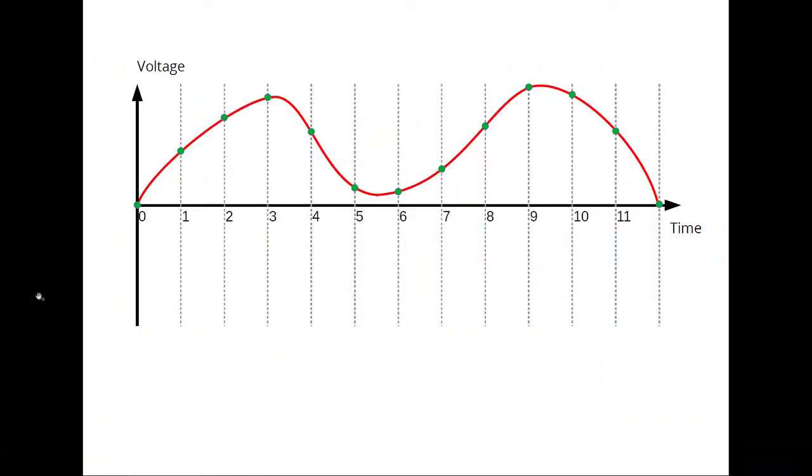So here we have a section of waveform which we've sampled, the samples being represented by the green dots, and we've numbered them for convenience. Let's say we want to play this sample back at 1.3 times the original frequency. Our output samples would now be the blue dots, which represent the sample points at 1.3, 2.6, 3.9, 5.2, 6.5, etc, etc. Unfortunately, we don't have waveform values for those points. Instead, we have to interpolate an approximation for these values, and we do this as follows.